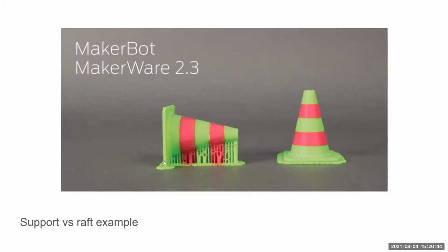But what this example is highlighting is that if you have a model that has some form of verticality, you can get a lot cleaner of a print if you print with an orientation that keeps in mind the physical limitations of your 3D printer. So if you're extruding molten plastic down onto a surface below where the printhead is, it makes sense to have this cone shape, because then you always know that there is something below where the printhead is for that nozzle to print onto.